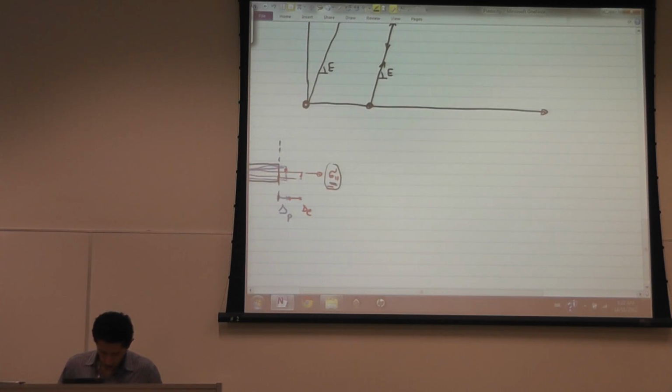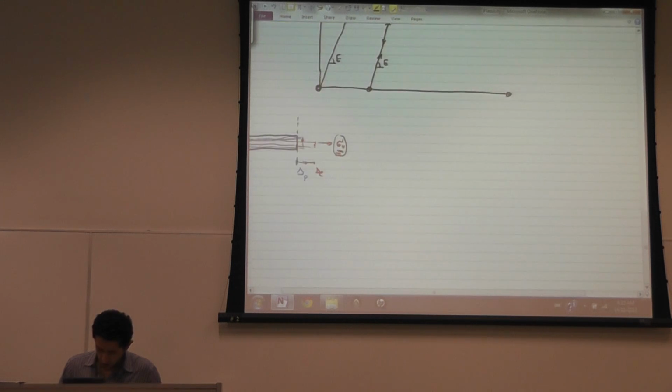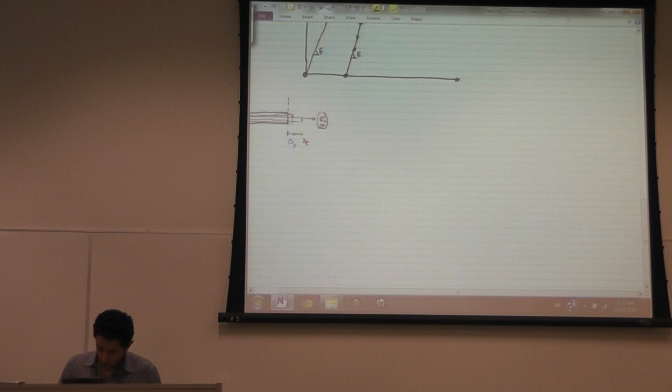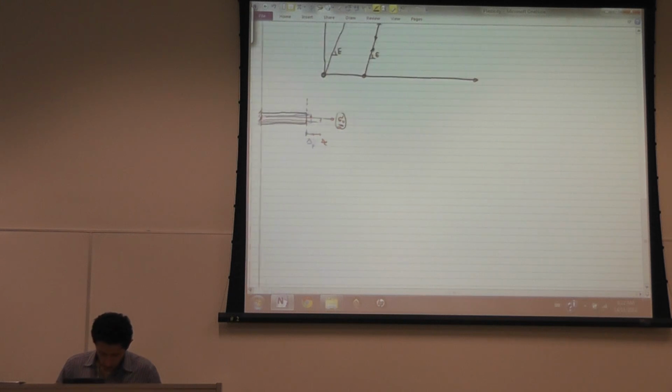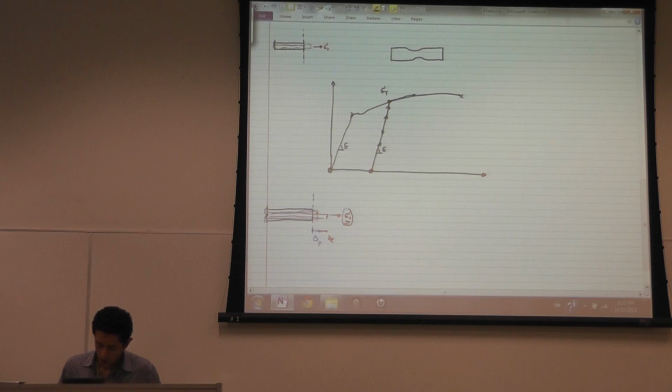And what happens is, as I apply plastic strain, or as I increase the stress and develop more strain, the sigma yield increases.